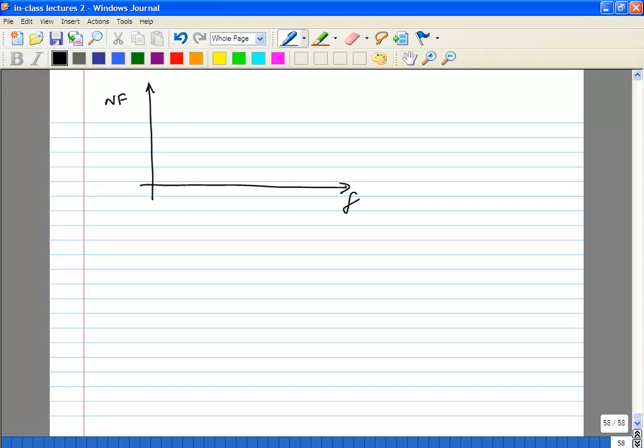It's not 3 dB actually. That is only if you are using a resistance at the input, right? For this one, Fmin is actually much smaller. It has some form 1 plus something, a lot of constants times omega over omega t. Remember that? We'll come to it later in today's class also. So it increases with frequency, maybe some kind of nonlinear increase.